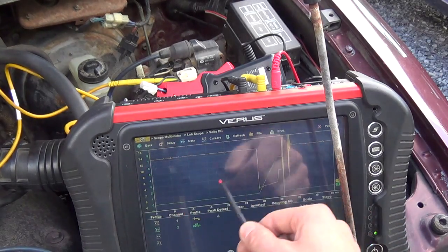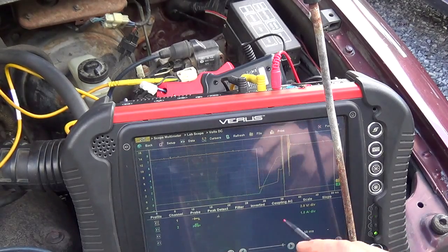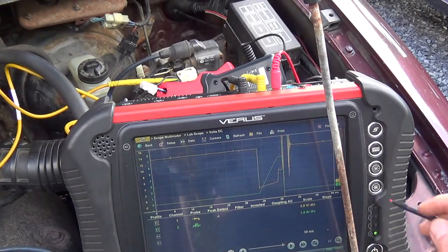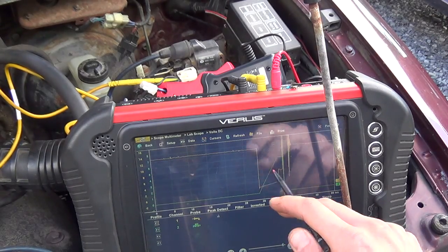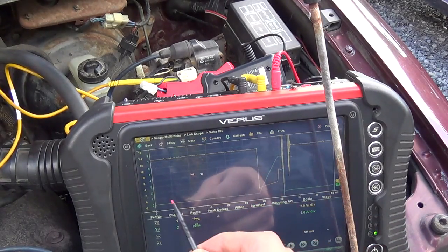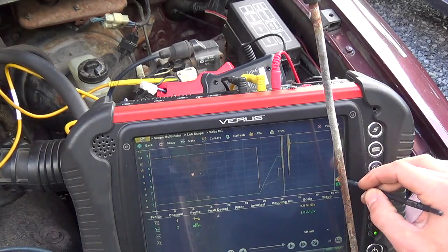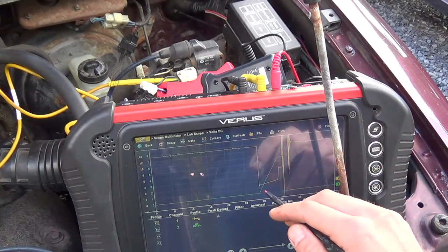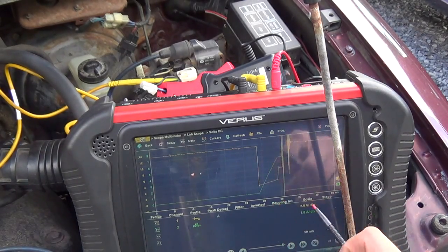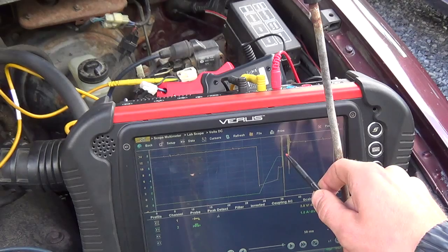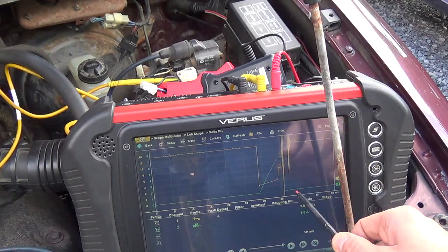When the transistor's off, there's no current, so there's no power dissipated inside the ICM. When the transistor turns on, that's when the magic happens, you know. So our voltage is dropping not quite to zero, so let's put that on the line here, okay? So maybe around 1 to 2 volts. And then here it's actually limiting the current. Maximum current is about 5.5 to 6 amps, okay?